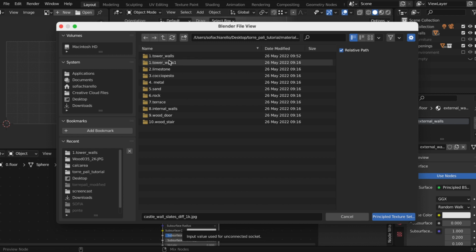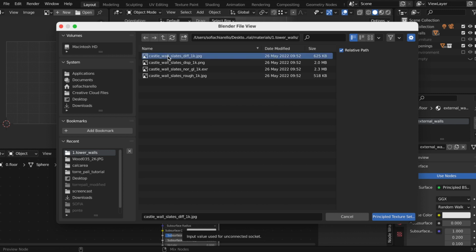We have to click the key combination Shift Ctrl T. Here we can see the list of materials that have been downloaded from the web that can be useful for us to complete the textures of our model. To select textures, we can click on the entire folder or manually select all the files. Accepting the inclusion of files creates a node architecture that we can analyze more specifically.